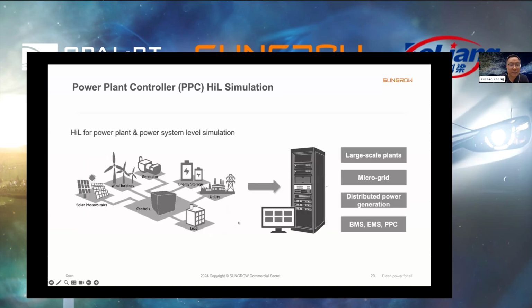And the second is power plant controller HIL simulation. In this case, we can build a microgrid or large-scale power plants in the OPAL-RT simulation system. And then we connect the real BMS, EMS, or PPC controller to the system to test their control algorithms.